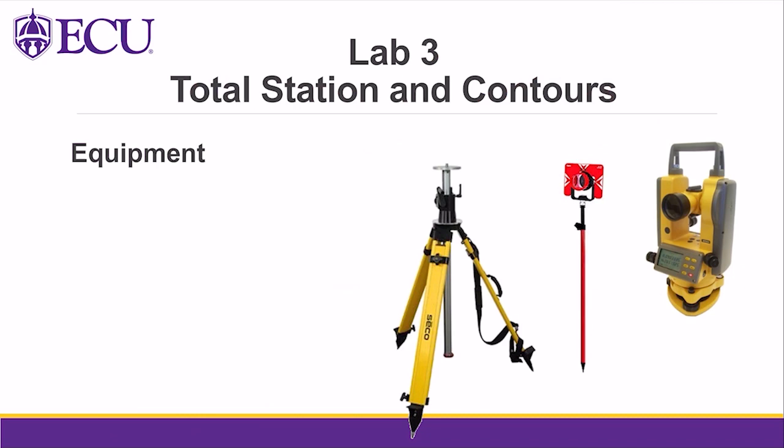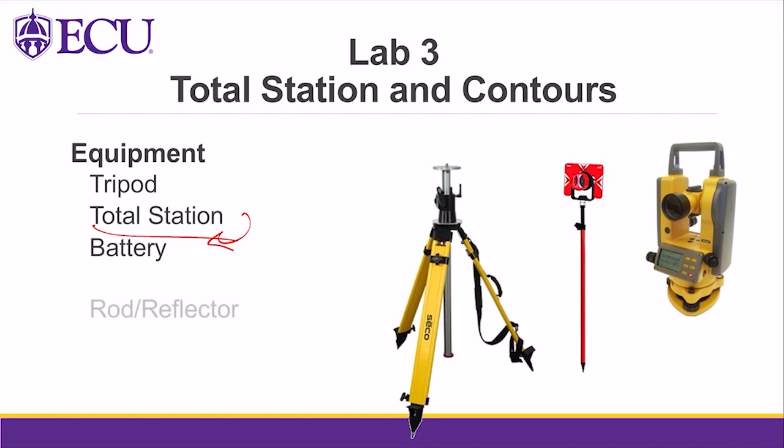What kind of equipment do we need? Obviously we need a tripod to be able to set up the machine. We need a total station. The total station needs a battery. It's a very essential part of the machine, and you need to take care of that. Make sure it's charged. When you go outside and do the surveying, especially if you do professionally, you have to have a spare battery in case your battery fails or it dies. Then you have another battery to continue working or surveying. A rod and reflector and Plumb Bob.